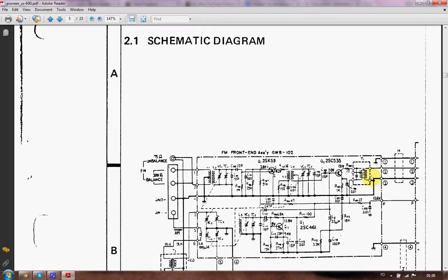If you put direct current to a speaker, it will just push itself out and if it's too high, it'll destroy the speaker. If you put only some direct current to the speaker, which it actually can withstand, it will push itself against the magnet because the coil gets live, and as soon as you break the circuit, it will retract to its original state.